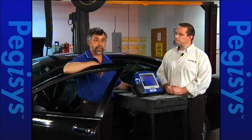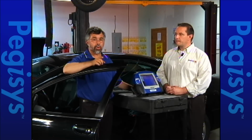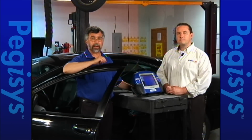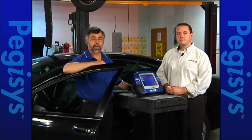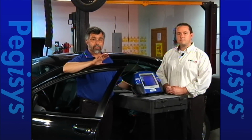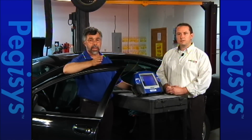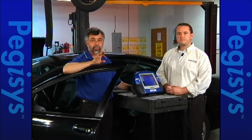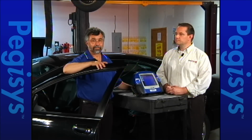It told us again to check diagnostic trouble codes, but it also told us to remove the M1 fuse. What that did was recalibrate the climate control module. Now, technically put, we had no fault codes, nothing electrical, so basically our doors were out of whack. The doors for changing from heat to AC were telling us no performance, no heat, no AC at all. So we recalibrated the climate control module and the car runs perfect.